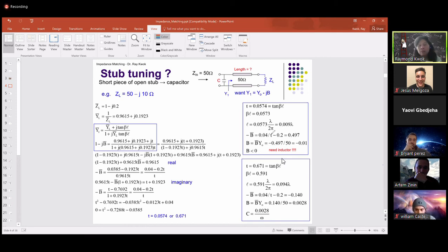Those circuits are more like crystal type, very hard, more like glass. If you want to drill holes in it, you have to be very careful. You can easily crack the glass or the substrate, and that becomes useless. So drilling holes in a hard substrate like alumina is a relatively expensive process.